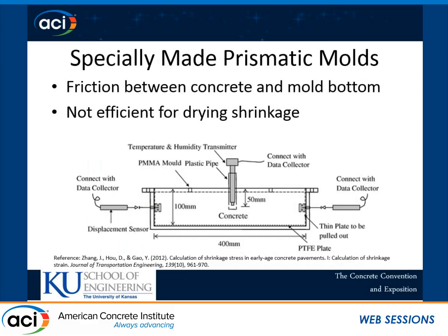Another test method is shown in the figure here. There are several variations of this setup, but the working principles are the same. Generally, the sides of the molds will be removed after initial set, and two displacement sensors are connected to the specimen. For consistency of the measurement, the specimen is also usually left in the mold, and the sensors need to be somehow connected to the mold.